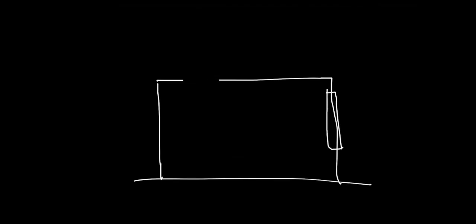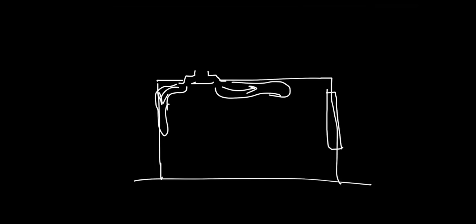Like supply grills, the diffuser's purpose is to spread the air across the unoccupied area adjacent to the ceiling surface to create induction of rising warm room air into the cool supply air jets and mix the two prior to the conditioned air stratifying in the occupied zone.